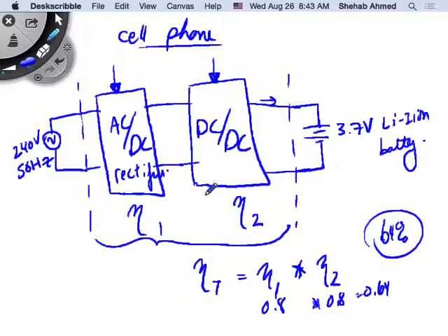And with this AC to AC conversion, I assumed that I can live with maybe a simple AC to DC rectifier, an uncontrolled rectifier here. Simple, very simple, uncontrolled topology that is producing some DC that is not controllable. I can go with a more complex AC to DC converter topology and eliminate this. Right? You can do that, but it's a more complex topology.